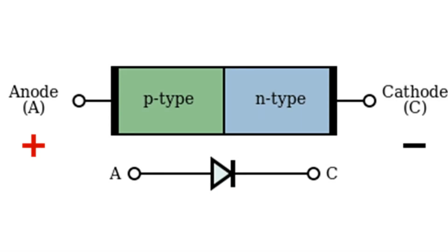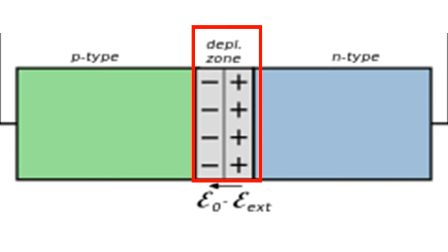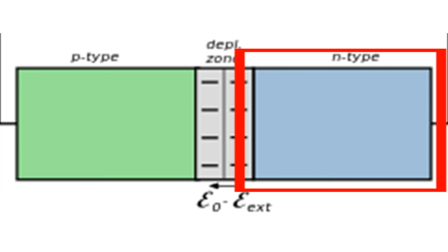The point is that when they manufacture both halves of the diodes of the opposite charge in such a way that both halves come into contact, they create what is known as a P and N junction, as a result creating what they call a depleted region, a zero charge region between the positive half, which is the P region, and the negative half, which is the N region.